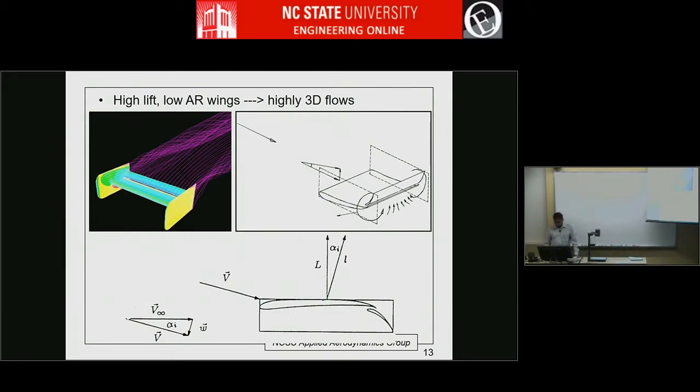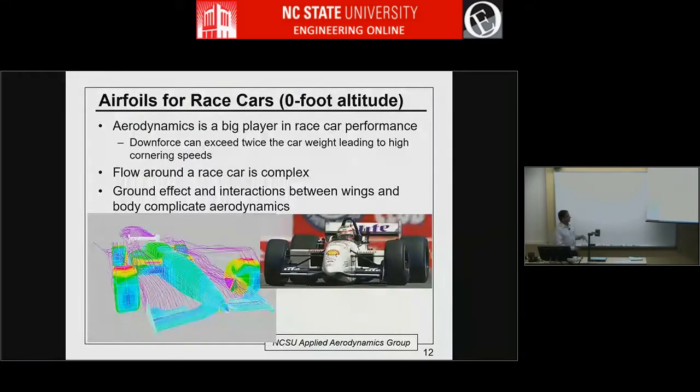And so here's one example where it's not just airfoil design, but at what condition you design the airfoil depends on other influences. Like here it was a short, stubby, heavily loaded wing, and sometimes there are all these things. So if you're designing the rear wing, you have the influence of the car body itself and the wheels. Those are all going to induce flow on the airfoil. So it's a really challenging problem.